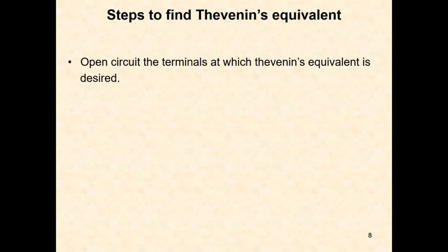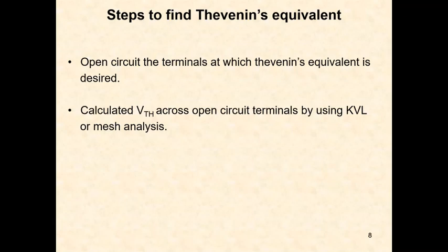So the steps to find Thevenin's equivalent. First, open circuit the terminals at which Thevenin's equivalent is desired. Calculate VTH across the open circuit terminals by using KVL or mesh analysis.